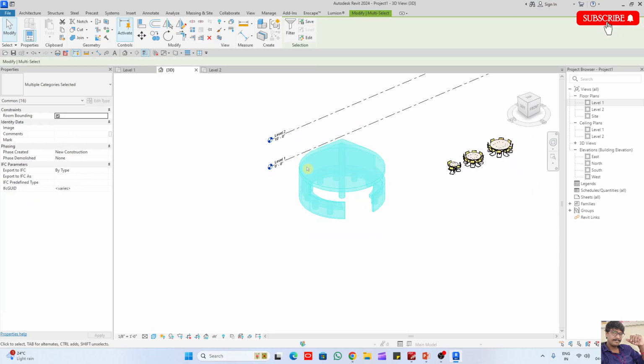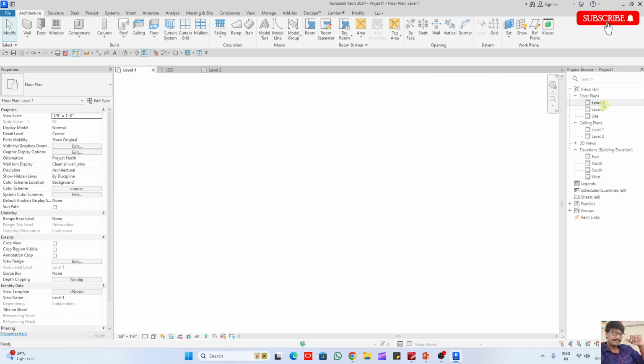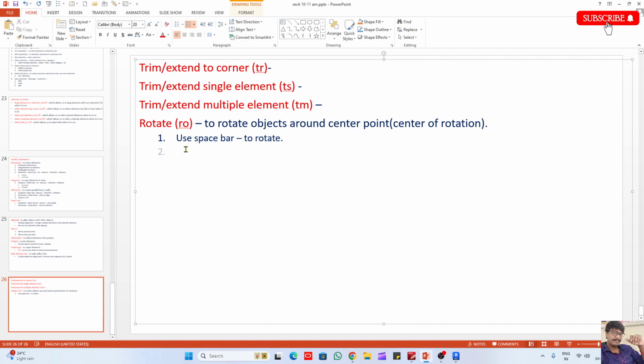So all will be done once you know. First, the rotate command. Okay, and using the snaps is also important. Practice this option, you will understand every example. You just have to know the operation steps. Clear? Rotate command. Select object, RO, specify center of rotation. How do you specify? Click on the place option, drag it manually. Sometimes you have to click on place, specify SC, and click on the element. The center of rotation will go to the center of the element you have selected.